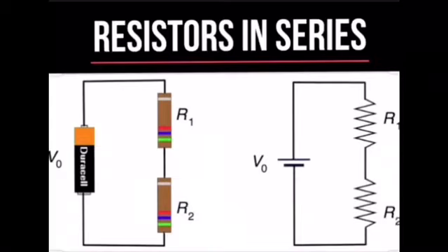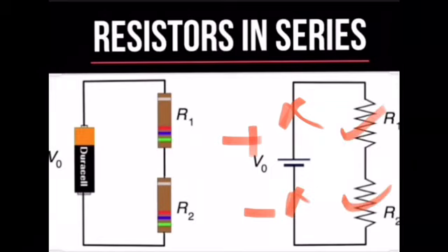This is a diagram. So this is positive, this is negative. The current will flow from this end to this end, isn't it? Now of these two resistors, if any one of them is burned or damaged, suppose this particular one is damaged, then what will happen? The current will not be able to flow from positive to negative. The circuit is not complete.